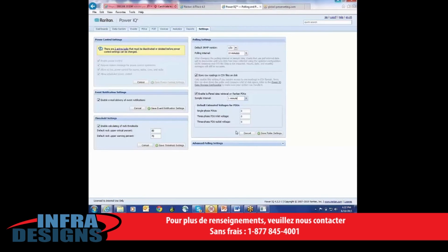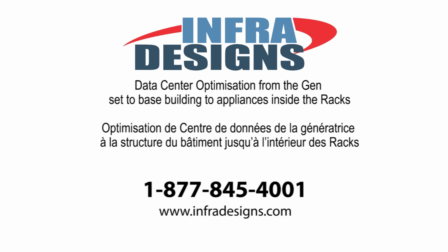This configuration is network friendly and resilient because the solution will only go out every 10 minutes to collect these 10 1-minute samples, but also if the network is down for an hour, no worry. The next time the solution connects to the device, it'll pull all of the readings from memory. And in this particular configuration with 1-minute samples, it has the ability to store 2 hours worth of readings. If I want longer storage, I can increase the sample rate, and if I made the sample rate 10 minutes, it could store 20 hours worth of data.